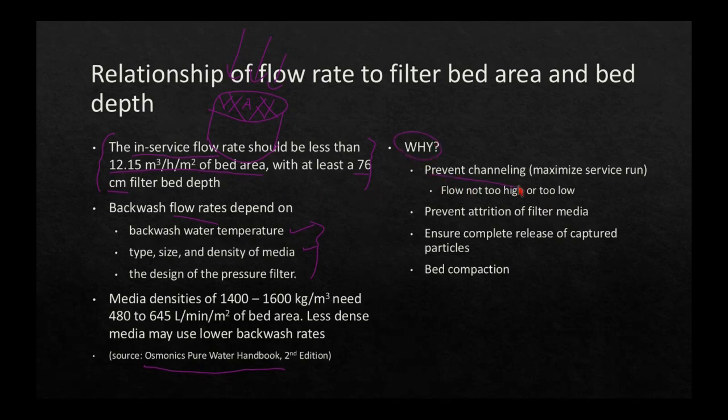So what's the importance of this? We want to prevent channeling. We want to maximize the service run. We want to prevent attrition of the filter media. Now, attrition means loss. And attrition is when we lose material during a backwash. And we don't want to keep losing our filter material. Plus, we want complete release of the captured particles, so we get proper bed expansion during backwash. And with the rinse rate, we want bed compaction.